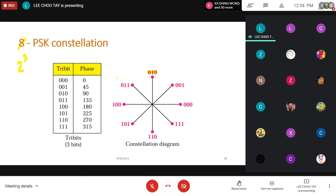Again, this is just an example. If the incoming carrier signal has a 0 phase shift, that means the binary information it is carrying is 000. It's carrying 3 bits here. But if the incoming carrier signal has a 45-degree phase shift, then that means this carrier signal is carrying binary data 001. Yeah, and the same goes for the rest.